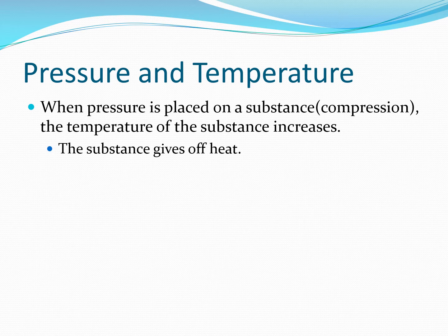Well, every cooling system in an automobile is under pressure. You look at every radiator cap out there, and it is a pressure radiator cap. We are putting the cooling systems under pressure, for example, anywhere between 12 and 18 pounds of pressure. And we've discussed in the past, for every 1 pound of pressure that you put on that cooling system, it raises the boiling point 3 degrees. So that is what's keeping it in a liquid state, because we pressurize it. You are keeping it from vaporizing.